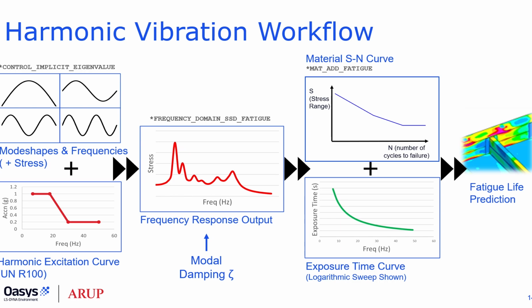We define this load curve on the frequency domain SSD fatigue keyword. On this keyword, we can also define modal damping for the analysis, which is usually a few % of critical damping for a lightly damped structure. We can also define where we apply the acceleration to the battery, which is usually at the mounting points.